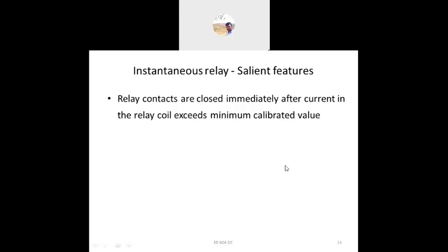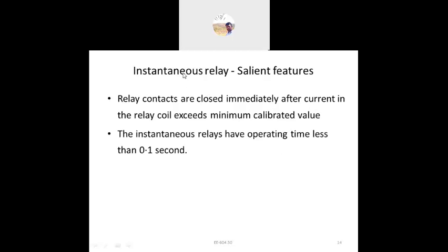If the fault value is reached, it will be closed immediately. The instant relay has an operating time of less than 0.1 second.